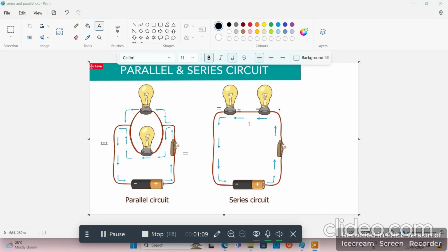In case of series connection, we start from the supply, same thing. After the battery, the switch is there. After the switch, the voltage we are getting is positive. That positive is connected with the positive of LED 1, and since positive is connected with the switch, we are left with the negative connection. Here you can observe that negative is connected with the other LED's positive. Positive and negative are interchanged in case of series connection, and then we are left with the negative. That negative will go to the supply negative.